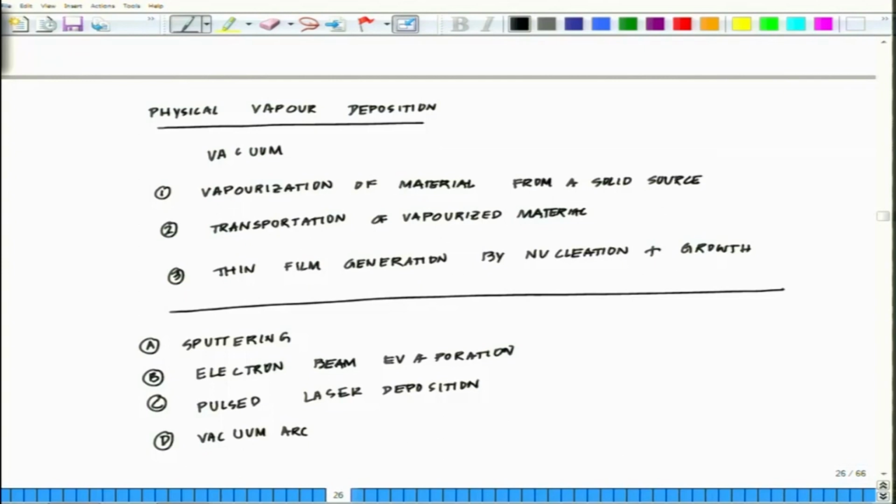Okay. Sputtering is a vacuum based PVD process which is often used to deposit films of nanomaterial, and sputtering works on the principle of momentum transfer, in which the atoms from the target, which is made up of the material to be deposited, are ejected by the ion bombardment. The deposition of material by sputtering can be achieved using DC pulse or direct current pulse, pulse DC or radio frequency.